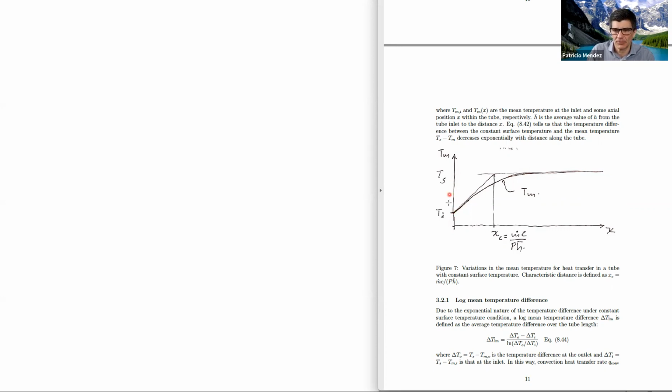So here the heat transfer is high. As the fluid is heating up, the heat transfer is being reduced. And by the time we are around at this characteristic length, right, for thermal equilibrium into the pipe, which has nothing to do with boundary layers, therefore has nothing to do with entry length, this other length is more or less the length you want in a pipe.